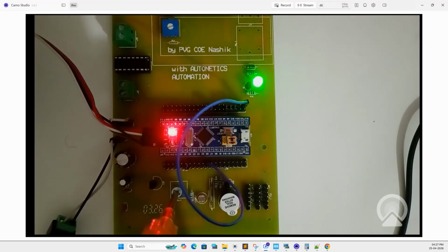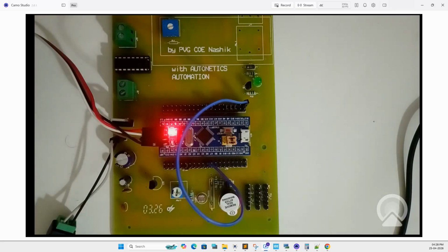Now we will save this code. Later on, using the same code, we are going to control the motor speed, after learning the motor interfacing. So this is how you can control brightness or motor speed using your PWM, your actual LED dimmers. Now there are smart bulbs whose light intensity can be controlled, colors can be controlled. So the same PWM signals are used for those. Okay. So we are going to see a few things in your next lecture.